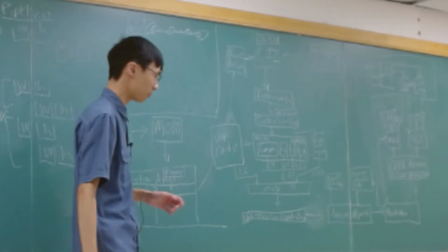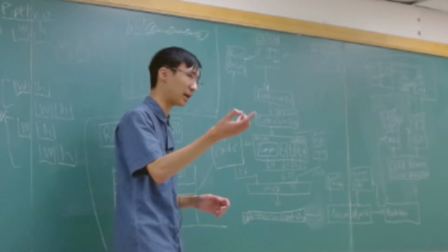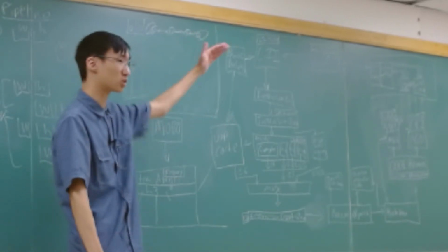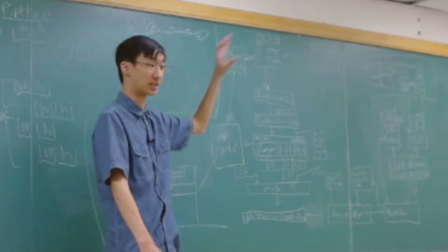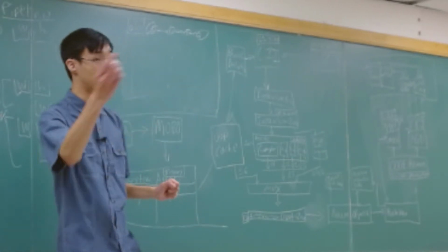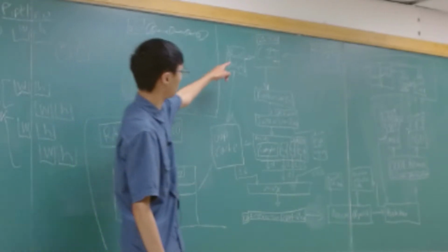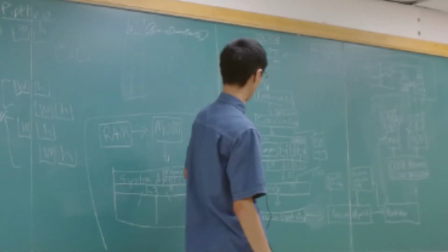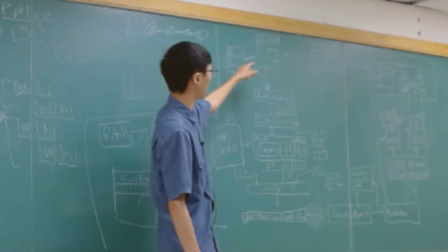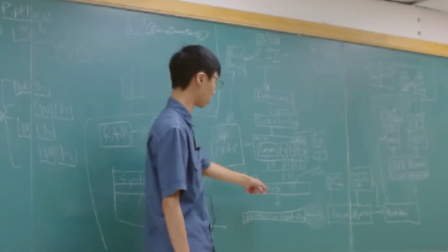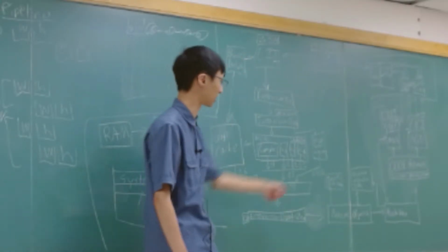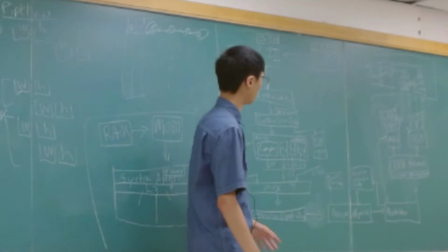Yeah, but generally, if you're a programmer and you want to write better code, then you probably do want to put the most likely, most predictable branches at the top, because that branch, you'll basically never get it wrong. And what does happen when you get it wrong is this branch predictor informs your micro-op cache or your L1 cache to tell you, hey, you need to run the fetch, or you need to push that data out because you hit this address or something like that, and you need to push that data into the rest of the CPU.